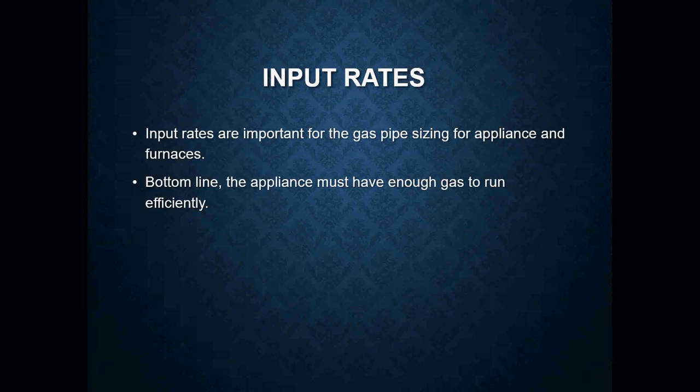Input rates are important for a lot of reasons, especially for gas pipe sizing for all of your appliances and furnaces. If we do not size or deliver the correct amount of BTUs to that furnace, we're not going to be able to achieve the correct burn, and we're not going to be able to get anything to burn efficiently like we should. I will be covering how to do gas pipe sizing in a later lesson, but for the main point, what you need to understand is how some of these things are calculated and where things are coming from.